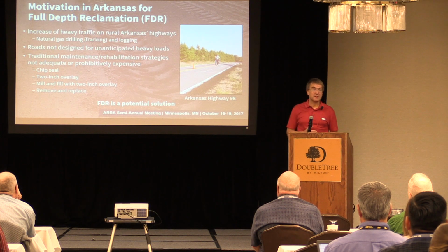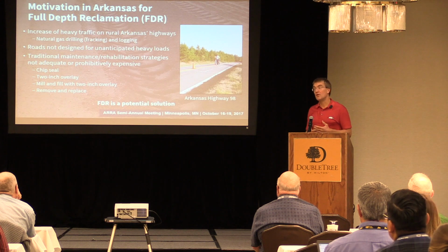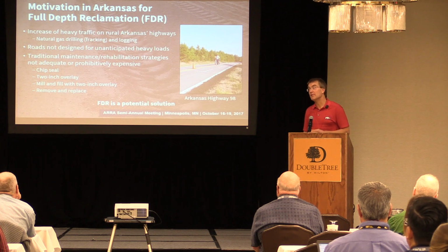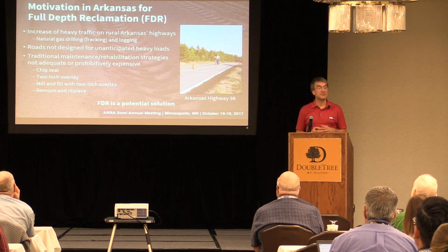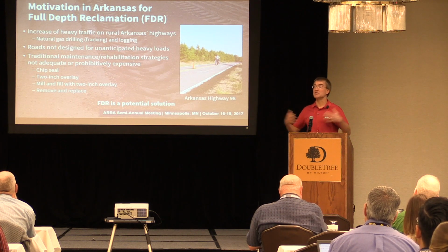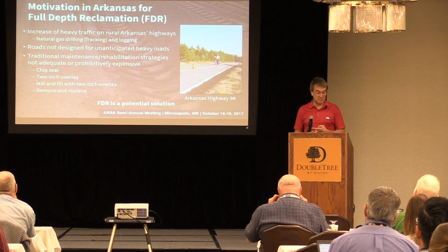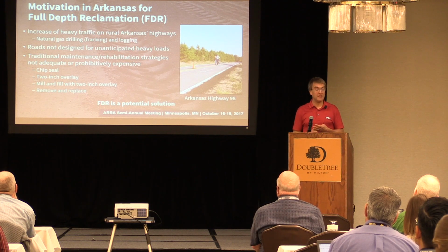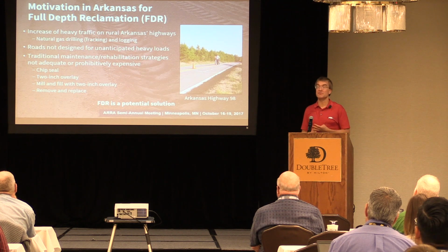And in the state of Arkansas, they have a relatively small toolbox that they use for pavement maintenance and rehabilitation. I was very jealous of Chisago County's toolbox. They use a lot more tools. In the state of Arkansas, we use a chip seal, a 2-inch overlay, a mill and fill, and a remove and replace. And that's pretty much all we use, which is unfortunate.